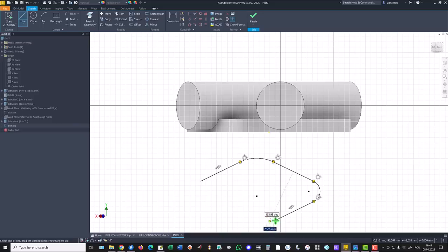You see, I finished the line. Now I keep pressed the left button. I go here. I align this and horizontal as well. Then align with tangency and with vertical at the end. Then I keep press the left button and I go here. You see that every contact is with tangency, but not this one. I apply tangency here.